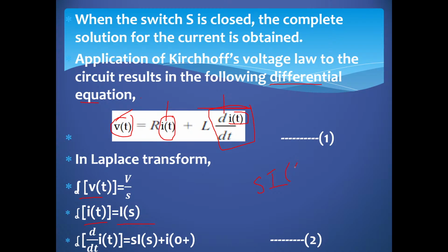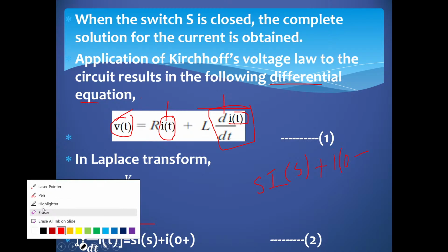But here we are writing this equation immediately after closing the switch. Immediately after closing the switch, when you take the Laplace, you must also consider the initial condition. What is the initial condition? The current in the circuit as soon as the switch is closed.